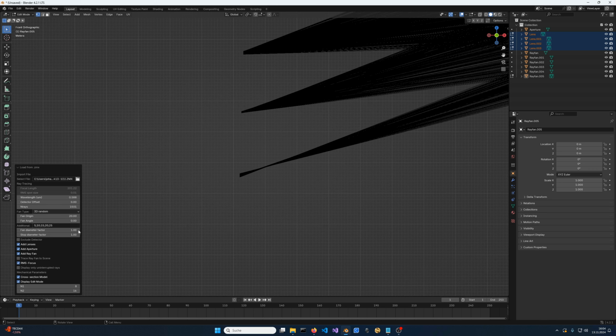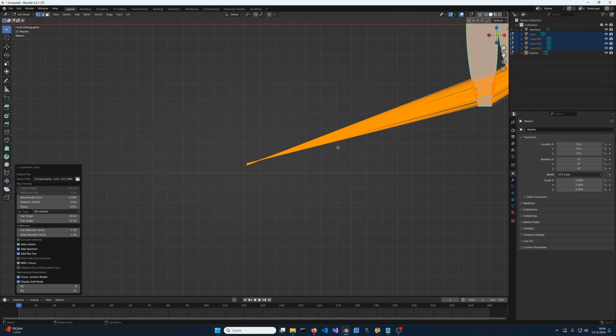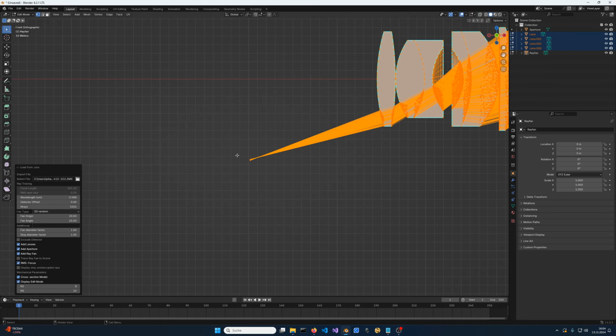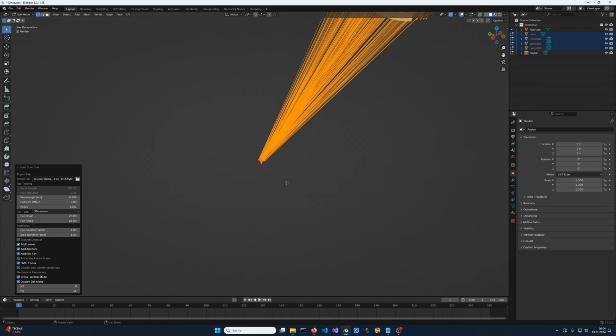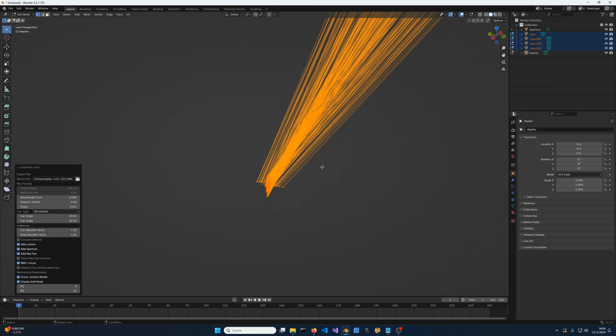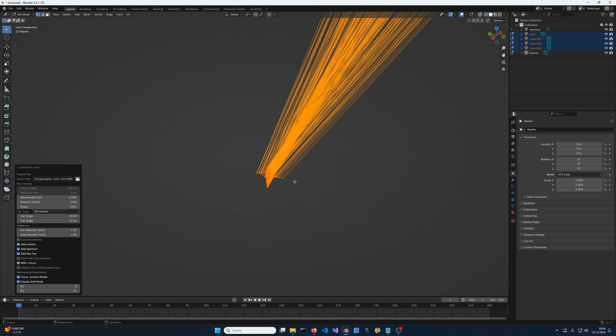But that is where the 2D, not only the 2D fan, but also the 2D side view will fool you. Let me remove these additional angles and just reduce to the single angle so that it is marked in edit mode. And when I now pan out into the 3D view around the focus spot, what we can see is that the rays in the plane that we looked at before, which is the sagittal plane, will focus somewhere over here, but the rays perpendicular, the tangential plane, would have a focus even further back. So actually with a 3D fan, this indeed is on average the best focus location.